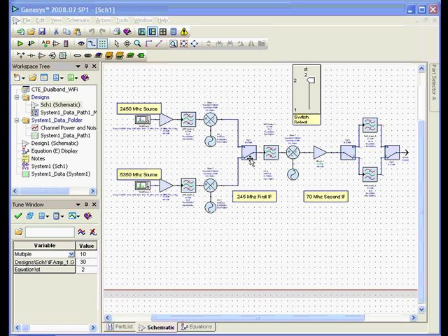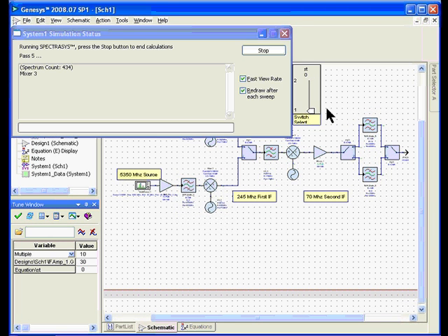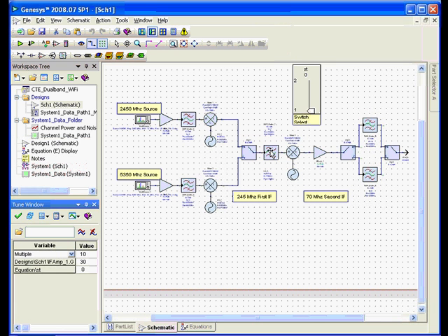And you can see these switches are all ganged with a slider here where we can tune between the two switches. If I want to tune the switch, I can move it to position 1, and you can see that the whole circuit will resimulate. Only takes a few seconds to resimulate, and all of the switches switch to position 1.